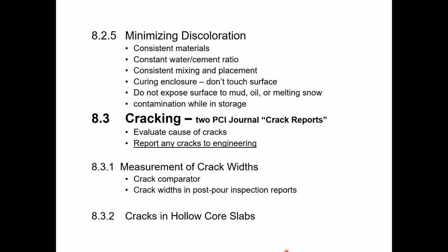You want to maybe have a curing enclosure that's going to protect that concrete from the ambient environment, to protect it from contaminants or lack of moisture or cooler temperatures. Don't touch the surface if you can help it while it's curing. You want to obviously not expose the surface to mud or oil or melting snow or any other contaminant that it might come into contact with when it's in your plant.